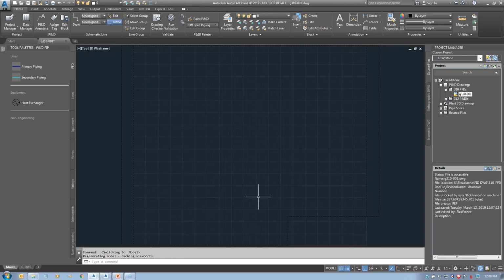Now I made it case 1. I'm going to do 2 cases, but I'm going to use the same drawing for both, because that's part of the problem, is the line numbering system. When you're doing pipes, you can't do multiple line numbers. So I have a system set up here where I'm going to be using a stream number as part of my tag that can be duplicated not only in the same drawing but in multiple drawings, and that's where the PFDs really start to click.